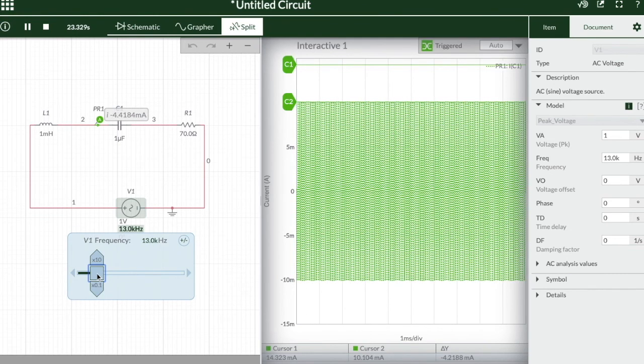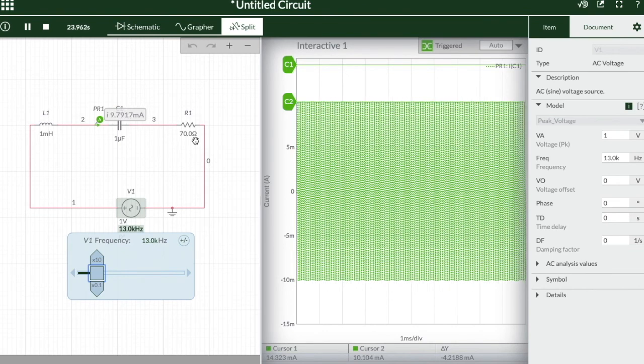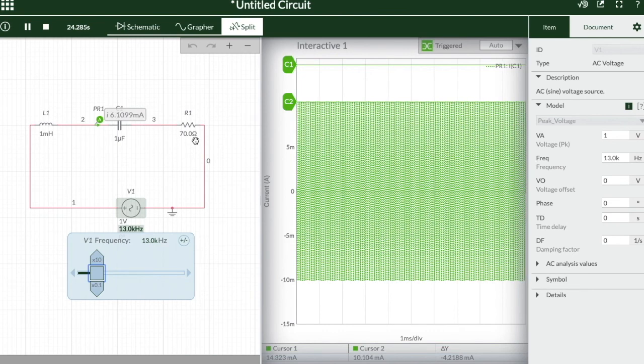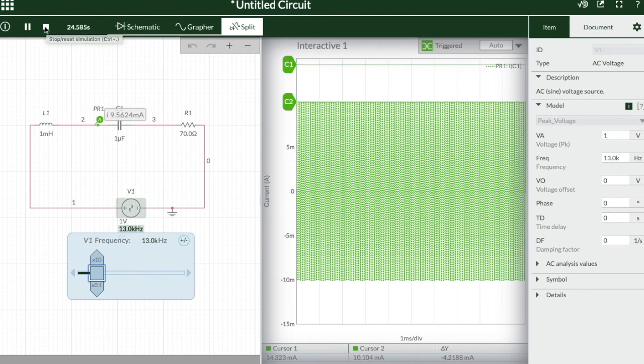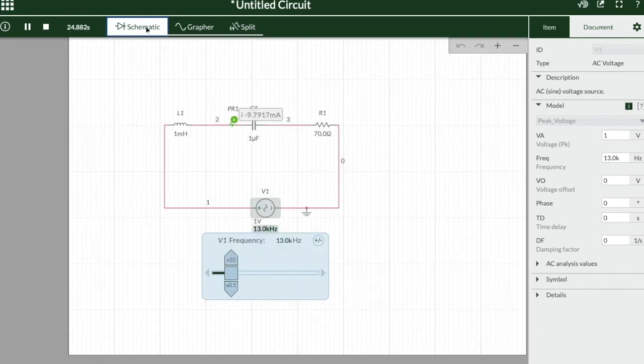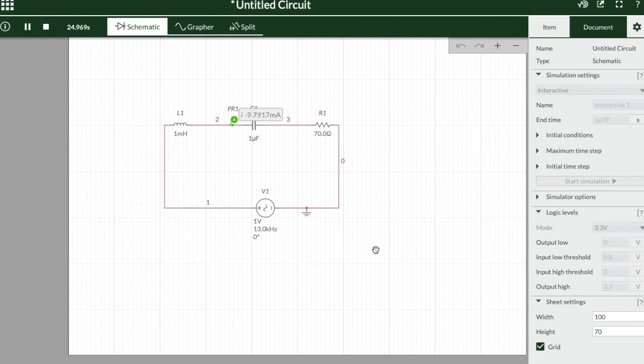So we can see that by decreasing the resistance, the bandwidth has decreased, but the resonant frequency has not changed. Thus, the quality factor of the circuit, that is resonant frequency upon bandwidth, will increase with decrease in resistance, making it a good selector circuit.